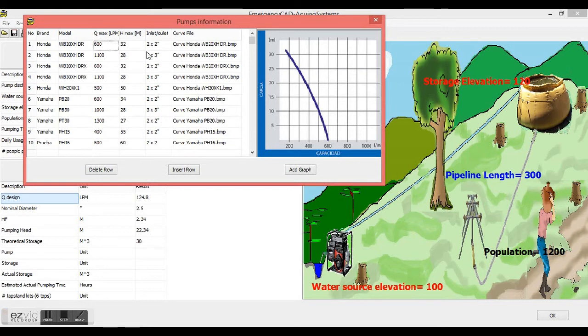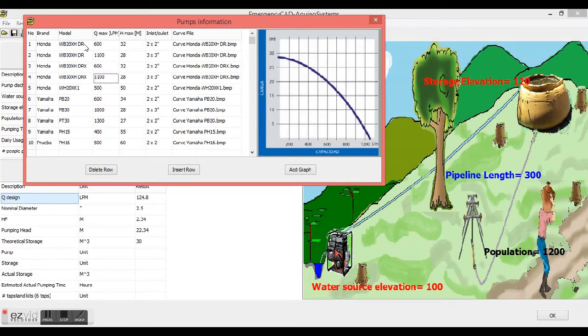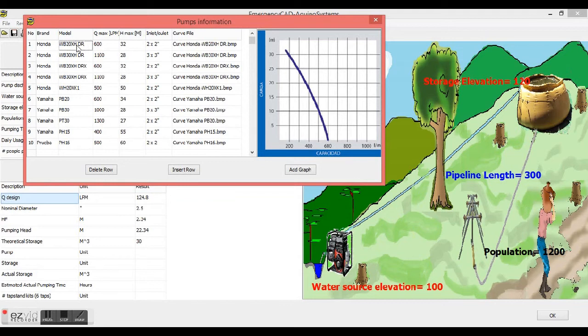Even if there are other pumps which can also meet these requirements, they are more powerful and therefore more expensive, which is why we use the criterion of economy by choosing a pump that technically fits what we need, but that is also the cheapest. In our case, we can say that the first one fills our requirements, both technical and economical.